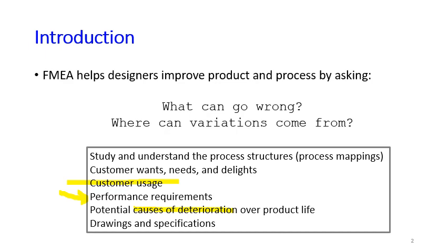And then to understand what can go wrong with a product, designers must also go back to the basic drawings of each component of the product to think about, oh, probably this can go wrong. Oh, maybe this part can fail if that happens. So designers really need to look at the drawings and specifications of each component of the product and really think about what can go wrong, what can fail from that component.